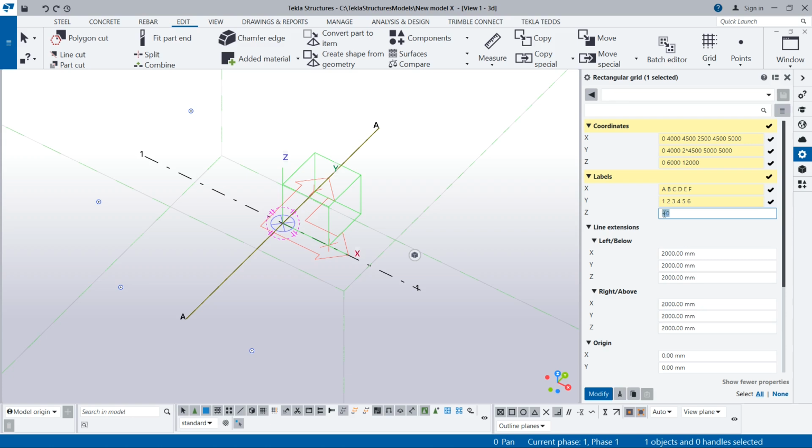Okay, you can see here that it is positive 0, and then space, we put positive 6, which are these values, then space, and then positive 12 meters. What this positive here means is that the grid system is going along the Z axis upwards, in a positive way. So if you put negative, it means that you're going downwards of the grids. Yeah, I hope that makes sense.